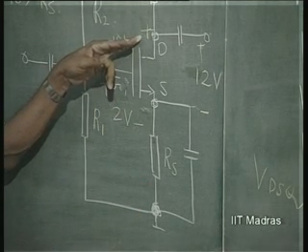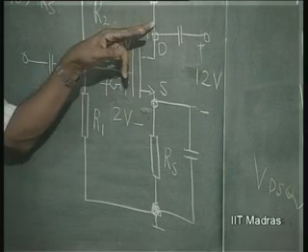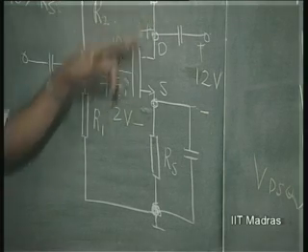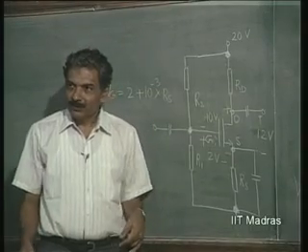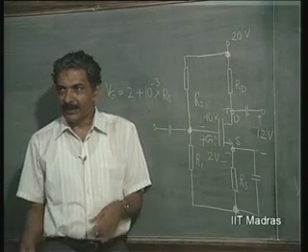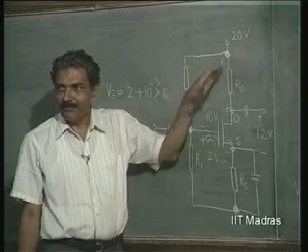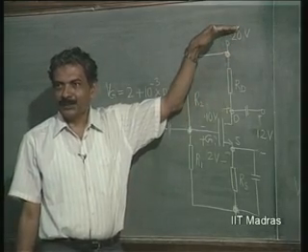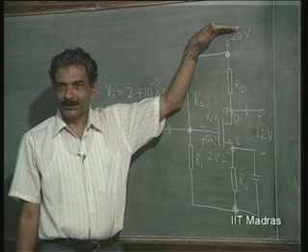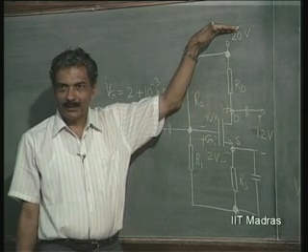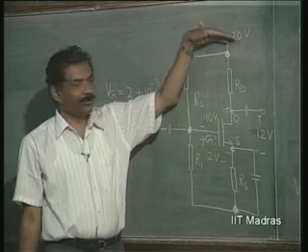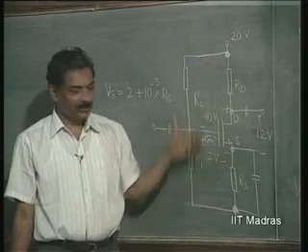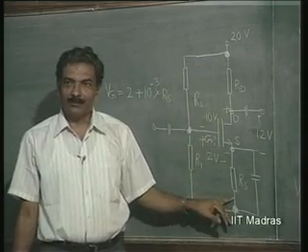So, you have 32 volts, and then Rd whatever you want. That Rd into 1 milliampere will be the supply voltage here. So, I can select that supply voltage. Here the supply voltage is restricted, therefore, you cannot make this operating point very stable.